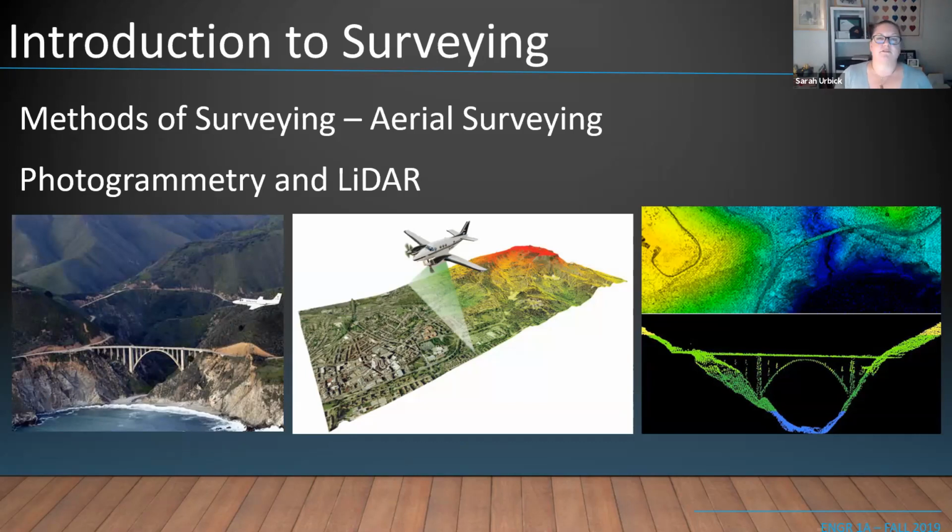Earlier methods of aerial surveying, if there were dense grasses, I mean, if it had been a wheat field or a hay field, and there was still all this grass all over it, tall weeds, that could throw off the survey. We may not have the right elevations. Your elevations could be wrong. So there were detriments to the validity and the accuracy of the aerial survey.